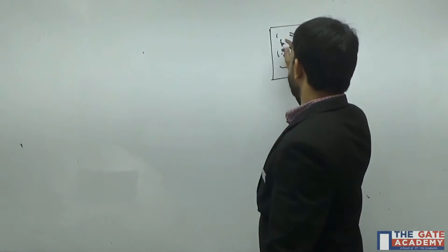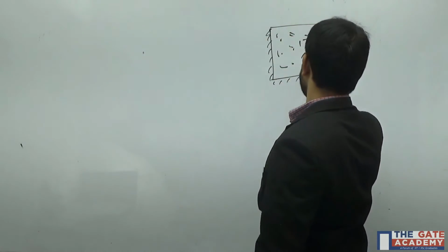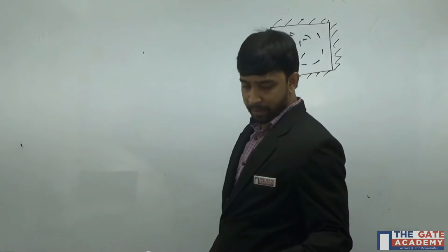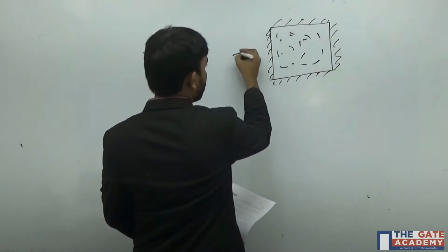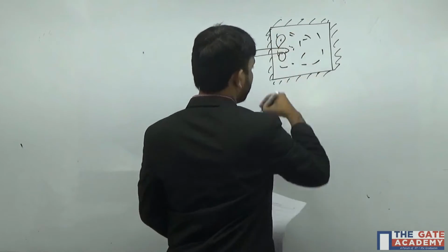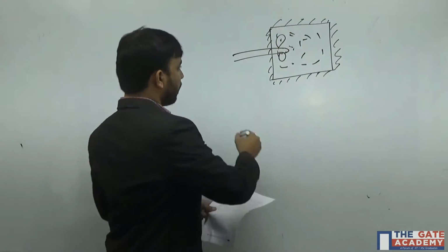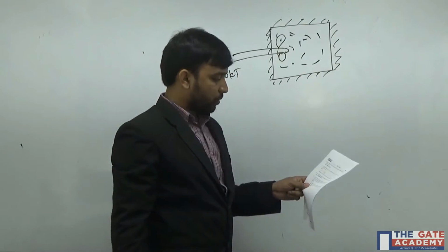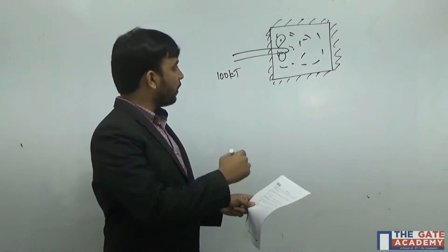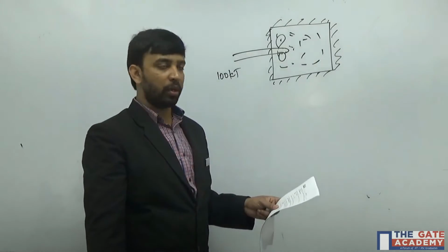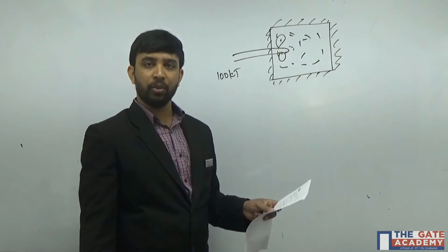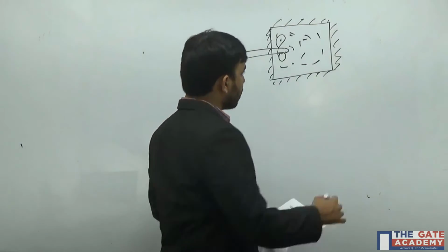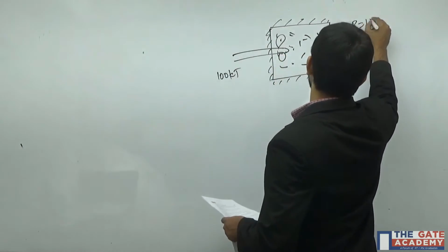Okay. So he's saying that it's an adiabatic work. So I can say this rigid container is insulated, so no heat transfer from the rigid container. There is a stirrer, and he's rotating the stirrer, so he's giving some work input. The work input that is given to the air is 100 kilojoules. That will be dissipated into the air, and all the work is converted into heat energy, and thereby the temperature of air increases.